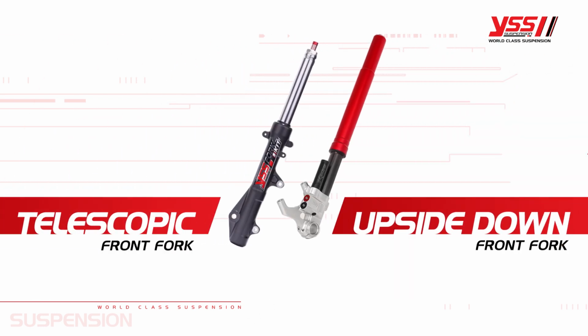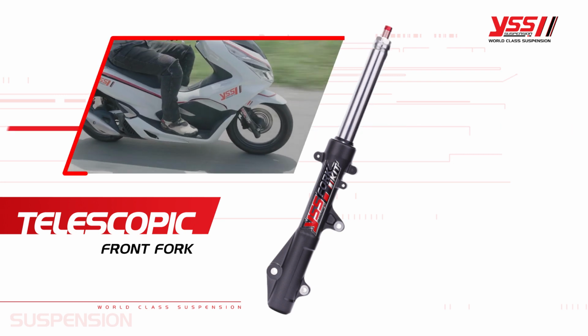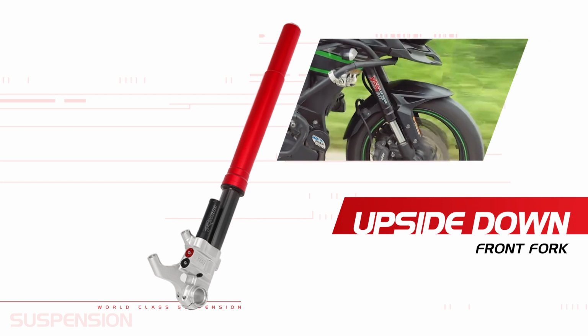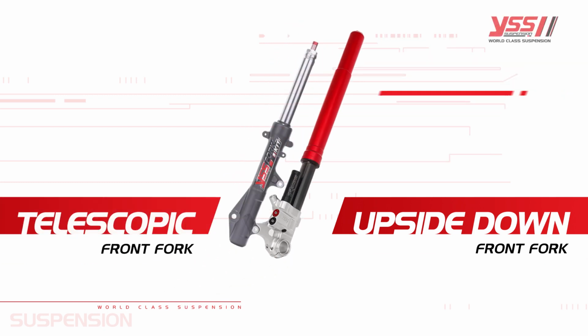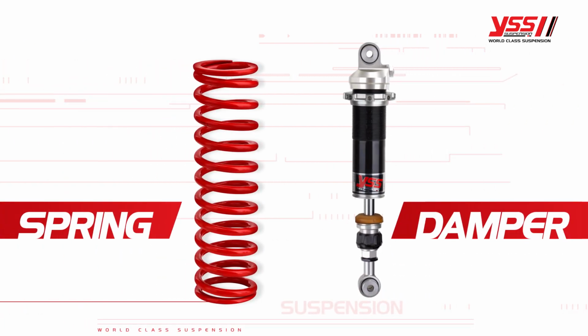Front fork absorbers are divided into two types, which are 1. Telescopic front fork, a front shock absorber system which has the fork tube at the top and the outer tube at the bottom. 2. Upside down front fork, a shock absorber system which has the outer tube at the top and the fork tube at the bottom. The components of a shock absorber are the spring and the damper.